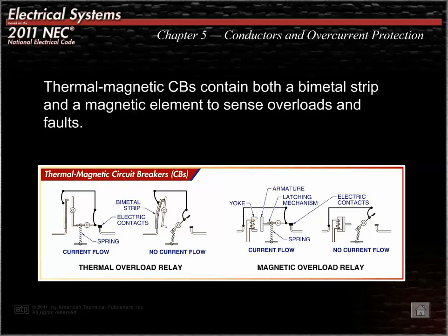The contacts are automatically opened by an overcurrent by a bimetal strip and/or an electromagnet tripping device. The contacts have 1 stationary contact and 1 movable contact. The movable contact is attached to a spring that provides a fast snap action when tripped.